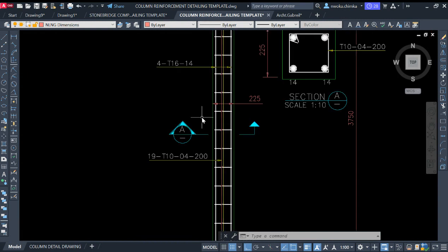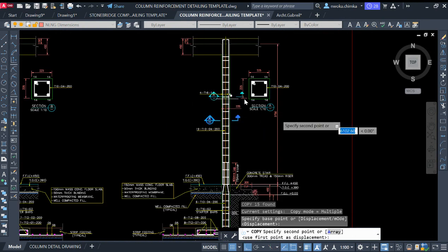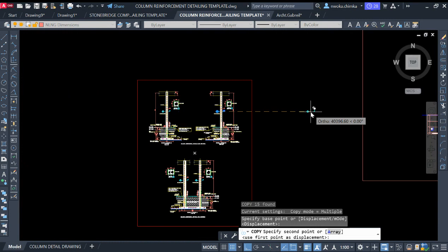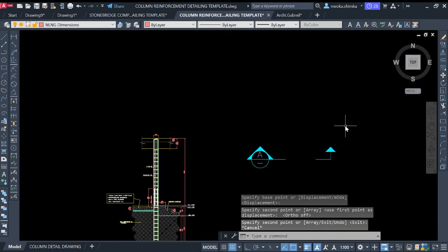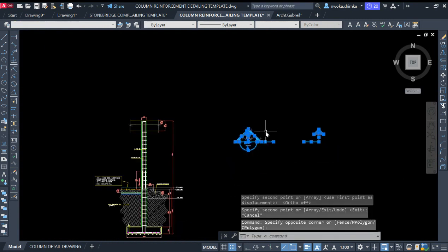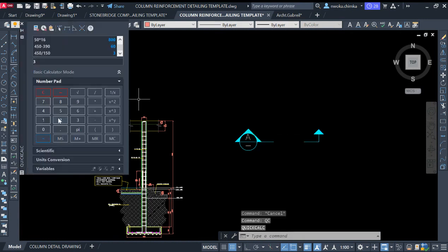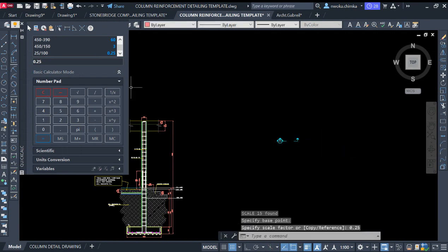So I can now copy just this one right here and copy this again. Just copy a bit. That's what you need this template for, so that this one can guide you on what to do. Okay, go again and then place this and just change this hashing. As I told you, if this diagram was scaled by 100, this one, I can say 25 divided by 100, I'll have 0.25. So I'll scale this back by 0.25.